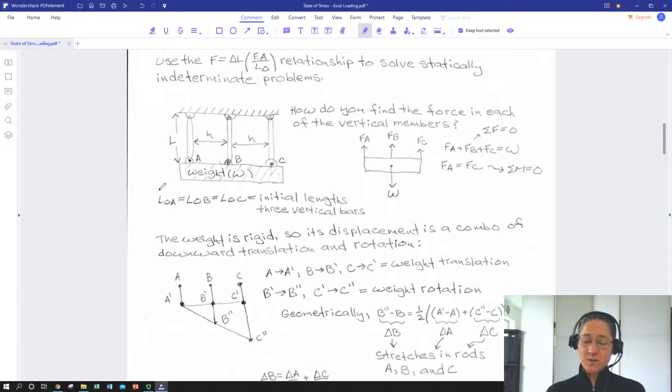We've looked at the difference between force and elongation versus stress and strain, with the former being dependent on material properties and geometry, and the latter, stress and strain, only on material properties. We've looked at how we can rearrange all the variables for those three expressions and arrive at a spring constant force-elongation relationship that lets us express force due to a given elongation in terms of some stuff we can probably look up or would have to know at the beginning of a problem.